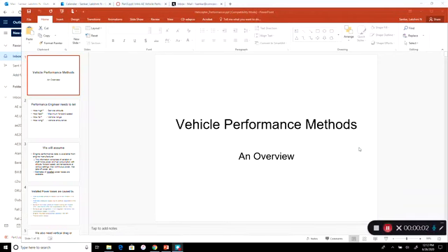We will continue with our discussion of helicopter performance. In the previous series of videos, first we looked at the vehicle in hover and vertical flight. We got an expression for how much power is required for a vehicle to stay in hover and also in vertical flight. Then in the second set of videos, we looked at forward flight. We found that the power is coming from the induced power because we are accelerating the flow, pushing it down to produce thrust. That's the induced power.